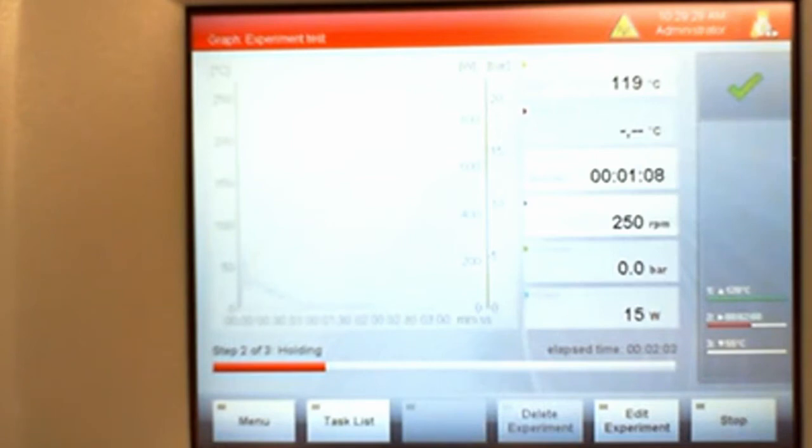According to the manual, the IR has an error of 5 degrees, while the temperature probe that you can insert inside has a 2-degree error. So it's more accurate when you use the probe. But at the moment, we don't have that possibility. Okay, thank you. No worries.